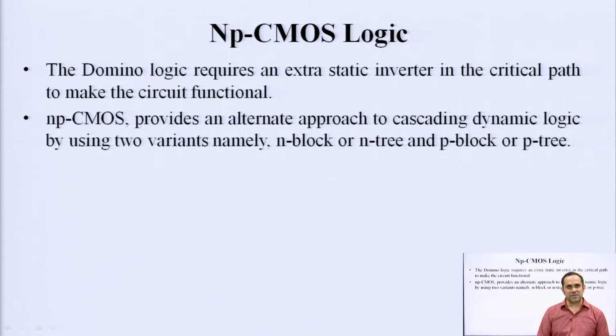There are certain cases where N type devices are very useful, but for those situations or input conditions when the N type devices produce a weak output, this is where P type devices can be used. So, one such technique which we are going to discuss today is what is known as the np-CMOS technique.